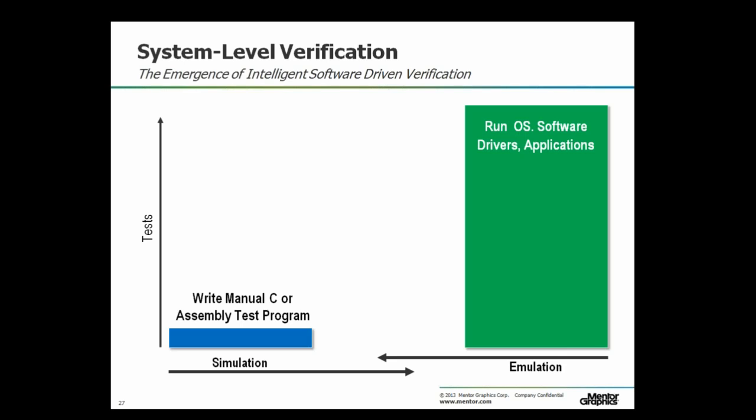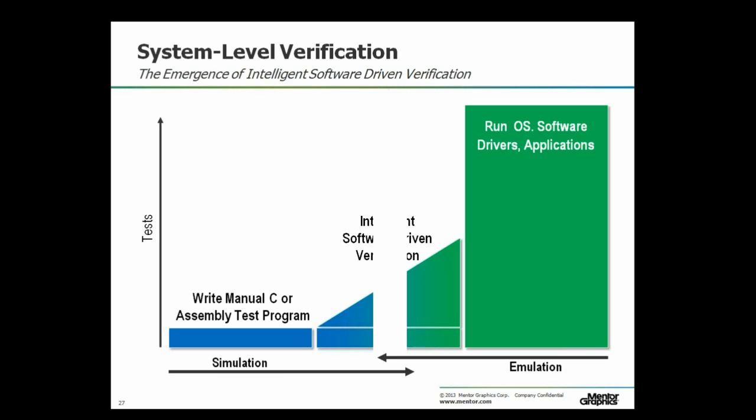It's very challenging. So one of the things that we're working on with the graph-based technology is bridging the gap in the middle and using the graph to automatically synthesize C-test programs that can be loaded into your embedded processor's memory and executed. And if done properly, this will enable you to create a breadth-first C-test environment as opposed to on the right-hand side where we have a depth-first verification environment where we can test all different kinds of modes, commands, connections, interfaces, combinations of things of your entire SoC.